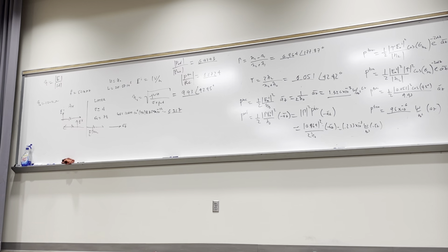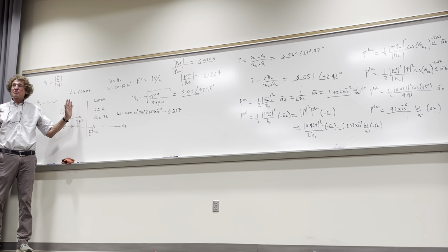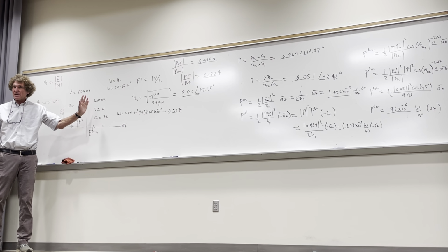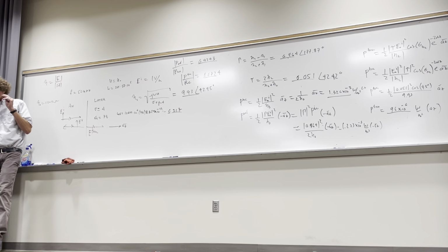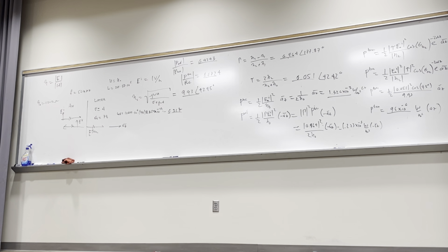The reason I'm mentioning that is oftentimes people will have an H field in the first region and then just multiply it by the transmission coefficient to get the magnitude of the H field in the second region. That's wrong. The transmission and reflection coefficients are ratios of E field, not H field, because η2 will change that. Just remember that. Gotta make sure I underscore that fact. Other questions? That's a good problem. We're just looking at ratios, but it tells you a lot.